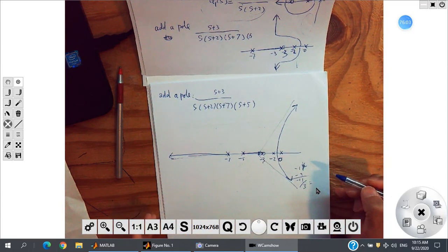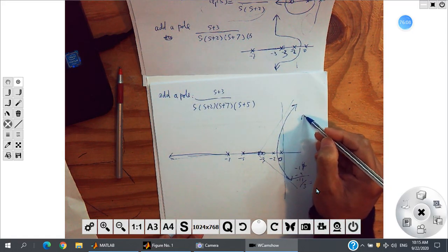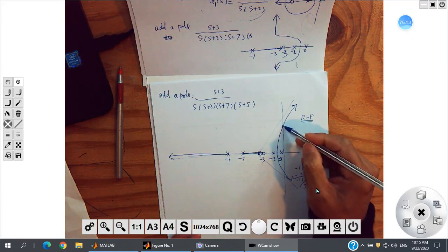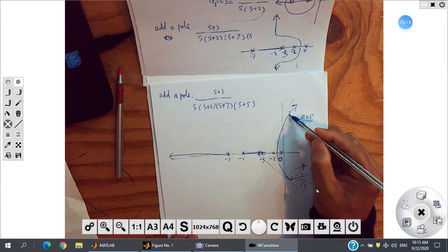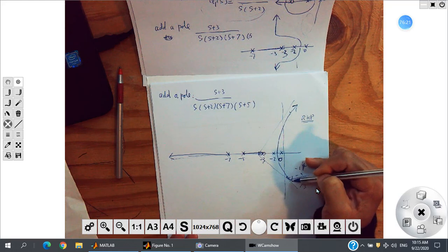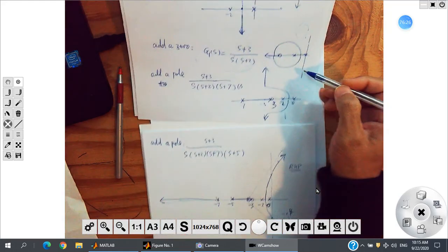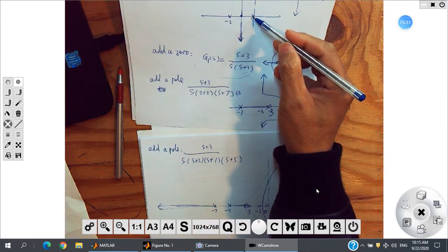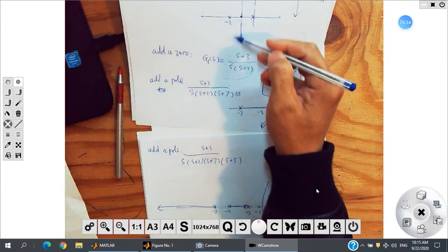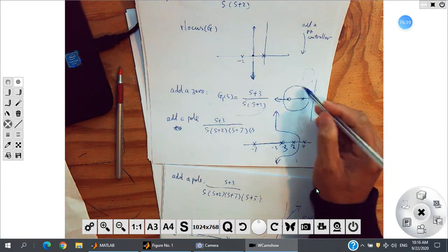You see, for this case, the root locus even goes to the right half plane. So you can imagine for large K, the feedback system will not be stable. We have some restriction on K. K cannot be too large. For the earlier cases, you can use any K other than zero, all the possible K's, and the system can be stable.